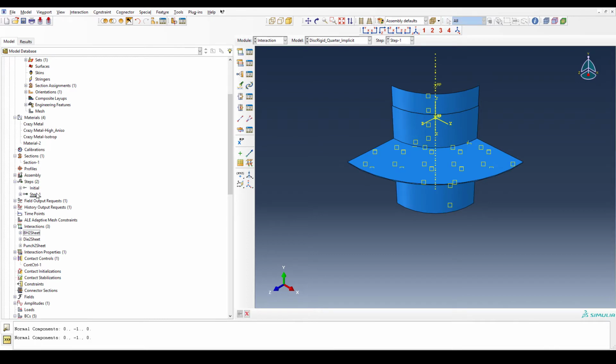I like to do a lot of things in one step because it is still the case that when you go for a multi-step simulation, for some weird reason, switching from one step to the next might cause some weird error. So sometimes just doing all your operations in one step might actually solve some issues that you wouldn't be able to get rid of any other way. So this is still a bit weird.